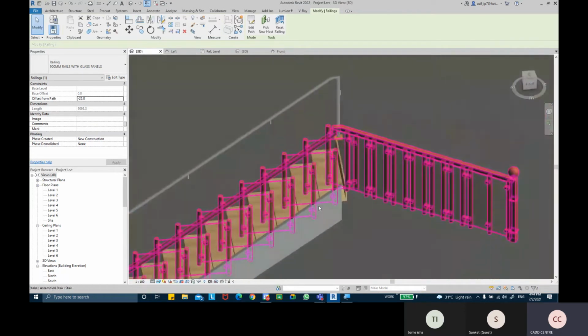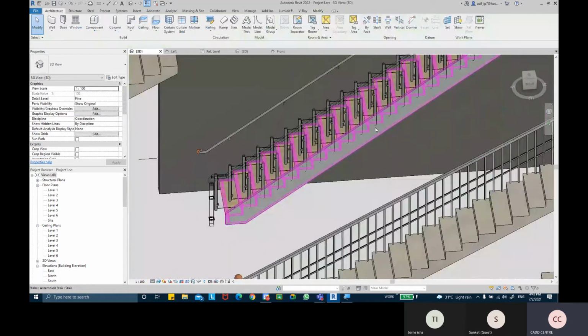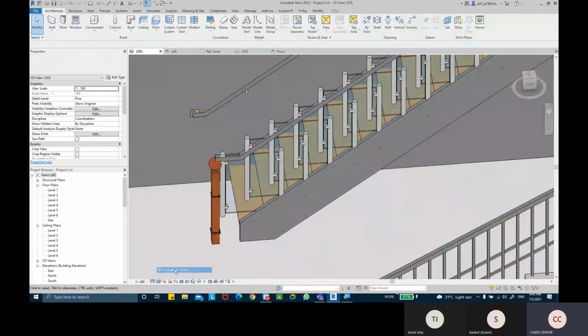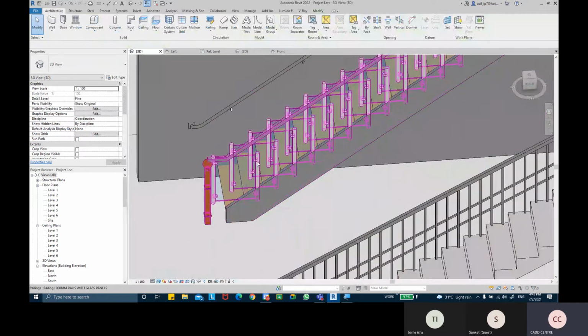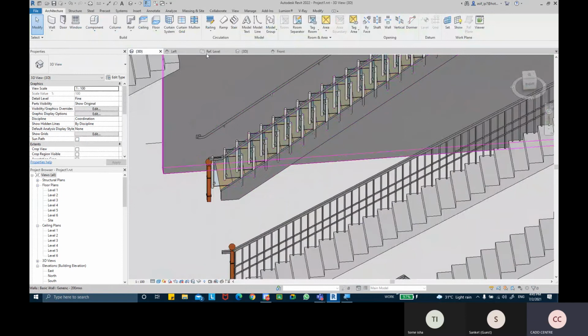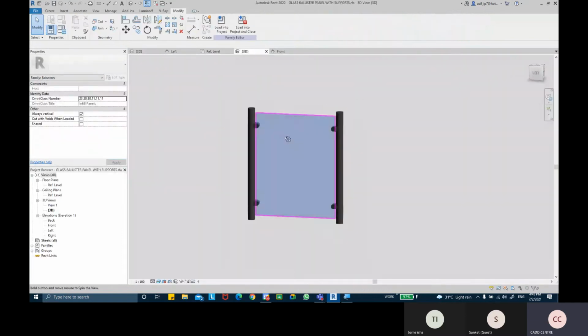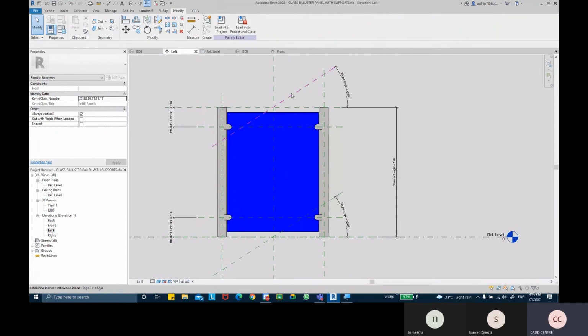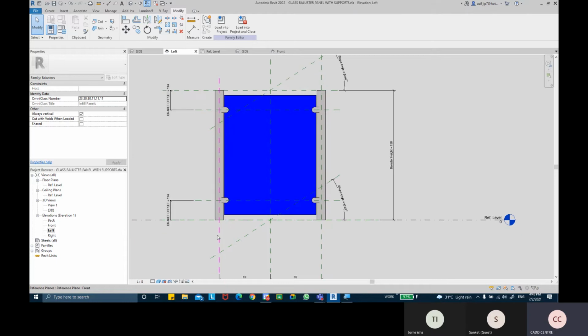I could try to, but this is where the error comes basically there. So you can see it comes straighter. It doesn't go slanted basically there. That's because when we created the family, we created straighter ones basically. So if you're creating for the stairs, you might have to create in the cross directions basically. Okay, so you don't need to create straighter ones. The only trick is that you just might have to create it in the crossing directions.